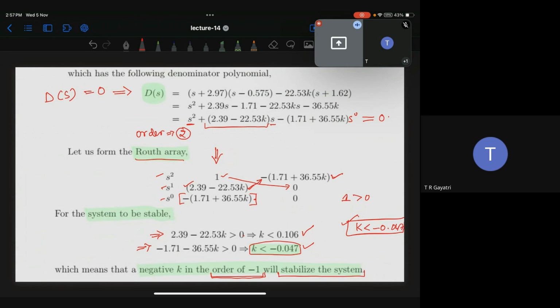But if the order is very high, as we also saw in the previous class, when you take a PD controller or PI controller, instead of K you'll have two terms, KP and KI. Yes or no? Yes, sir. So you need to find some region, let's say this is Ki, this is Kp, where both satisfy the stability property.